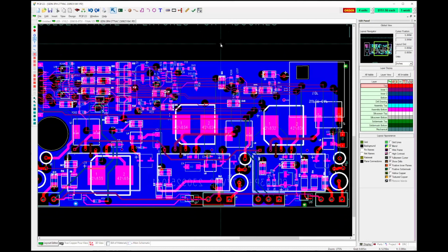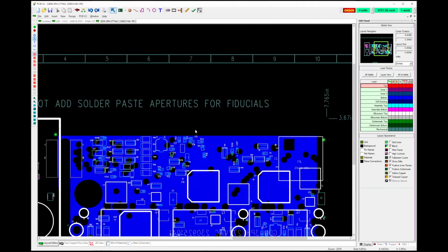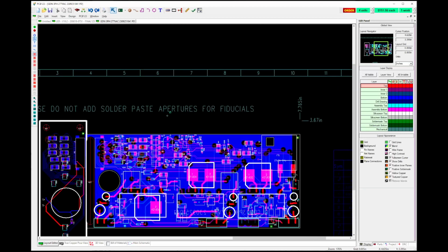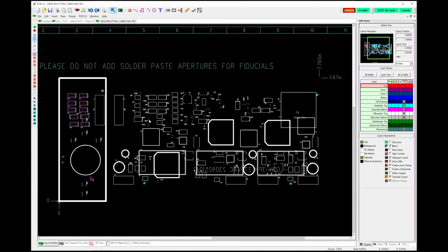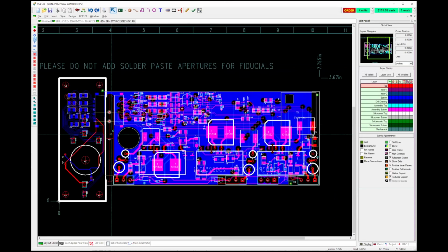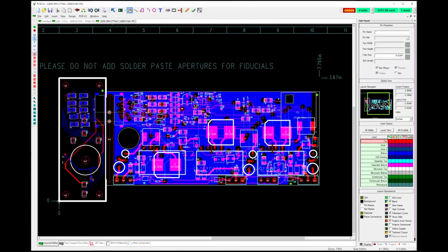Well, let's see. I've got a couple other questions. He said yes. Okay, good. How's a cutout different from a slot? I've entered slots by placing a pad, but not used the slot trick. Okay, so slots are just basically a pin, a non-plated pin that's defined using the add pin button. And a cutout is anything else that you want to cut out of the board. They only let you do rectangles or circles in the cutout command.